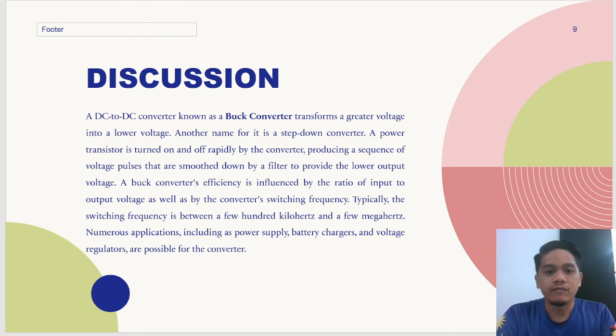A buck converter is influenced by the ratio of input to output voltage as well as by the converter switching frequency. The switching frequency is between a few hundred kilohertz and a few megahertz. Numerous applications, including as a power supply, battery charger, and voltage regulator, are possible for the converter.